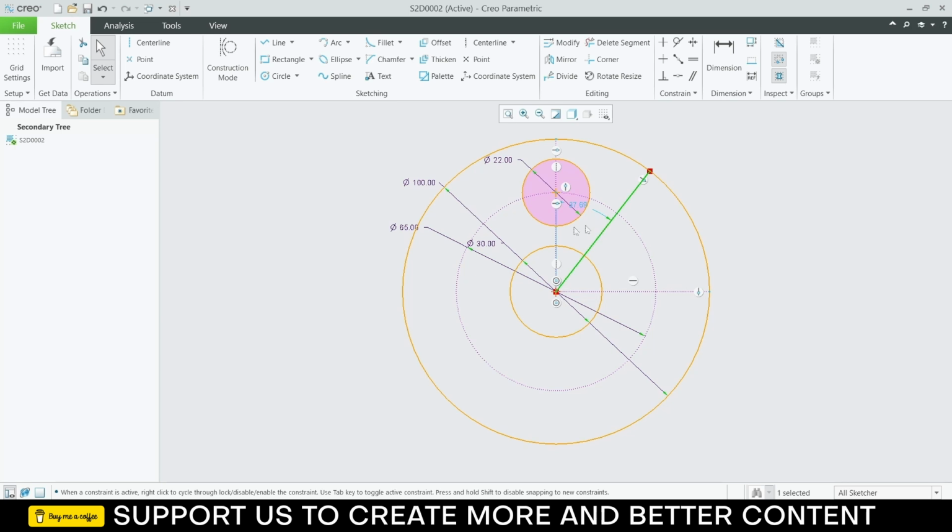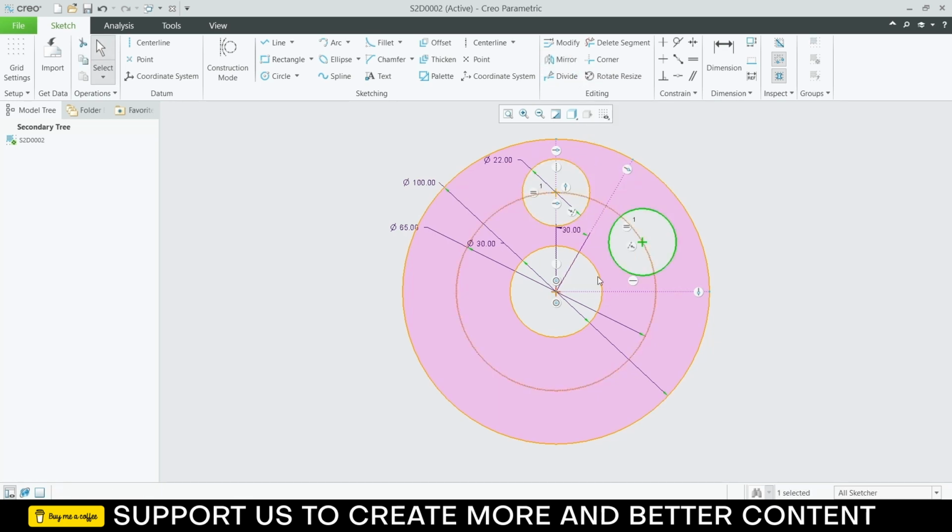Now I want to create a dimension that this line is 30 degrees to this one. You can see the dimension already here. So double click on it, 30 degrees. But I don't want this line to be in my geometry. So select this line, make it construction mode. Now what I can do, select this line, click on mirror and select this line.